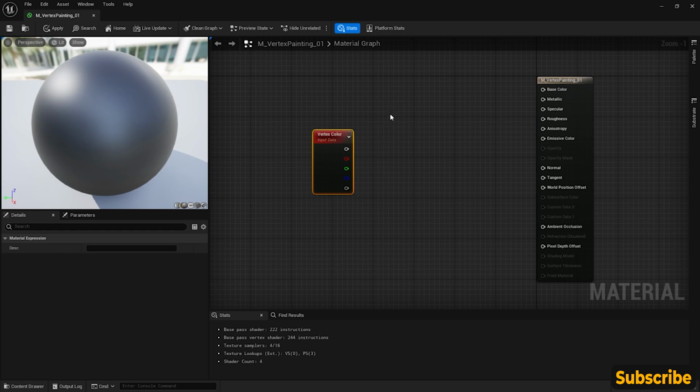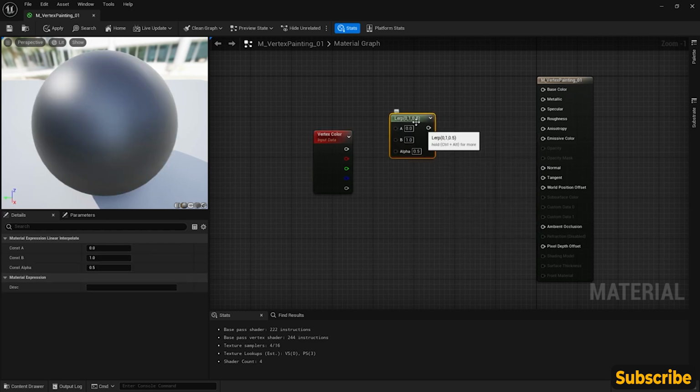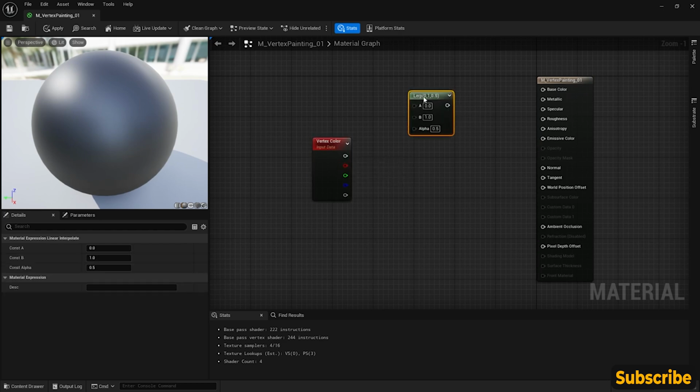So let's right click and type in LERP for linear interpolate. And we're going to use the vertex color to drive which material is seen. So again, let's do it with the red channel. We have basically 3 and 4, if we think about the alpha as well.